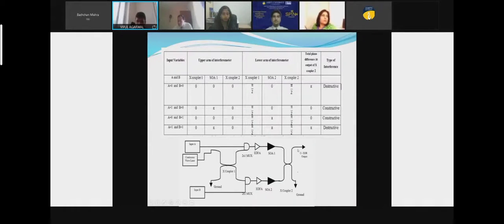So we say 1 is obtained, and if they interfere destructively, we say 0 is obtained. So the phase shift is designed in such a manner that the XOR logic table is fulfilled. You can clearly say whenever 0 0 is there, it's destructive. As you know, for input bits 0 0, output should be 0 for XOR, which means destructive. For 0 1, we are ensuring that the continuous waves have a phase shift such that they overlap constructively. So we obtain 1 here.